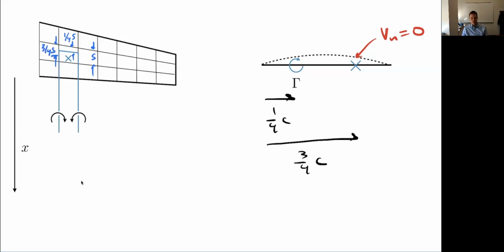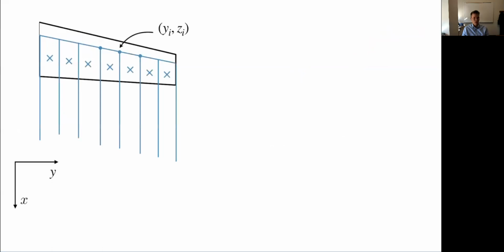So we're just basically utilizing that same idea, but extending it chordwise. In our case, we're going to simplify. We're not going to have chordwise panels, just only spanwise variations. This is also known as a Weissinger model. This is common for high aspect ratio wings, which is what most transport and many model airplanes and most general aviation airplanes are, fairly high aspect ratio, to where the chordwise variation in lift is less significant. We're mainly interested in capturing the circulation or lift variation along the span.